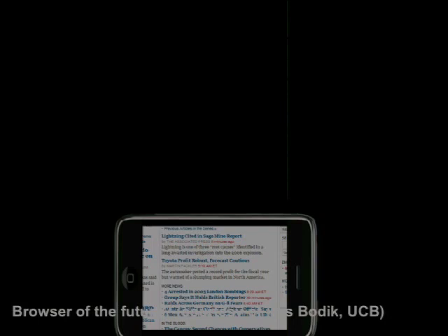So it's actually doing infrared illumination. And there's a camera in the Wiimote, an infrared camera, that spots these beacons. And that tells the system the position of the handheld relative to the screen. So the way that it tells that you're pointed at the screen is not using the accelerometer. Okay? In fact, it's generally telling position by looking. Well, it's combining the two pieces of data, but in any case, it tells the orientation of the Wiimote relative to the screen using the infrared camera more than the accelerometer.